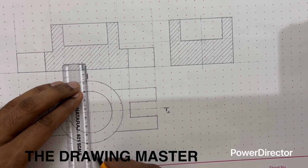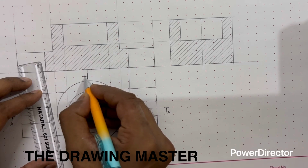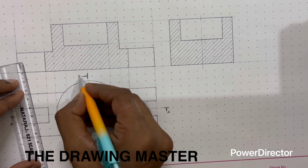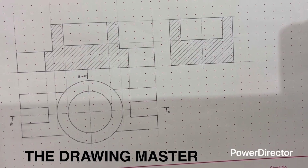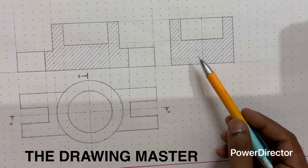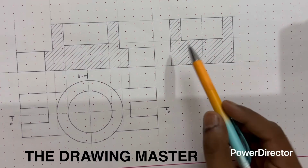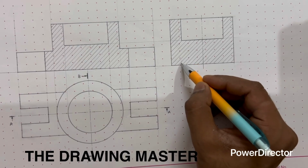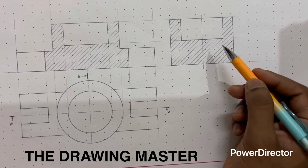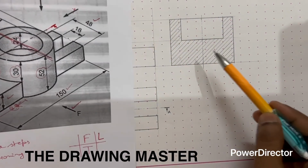This cutting plane line is very important. This is the direction of view and this is the name of the cutting plane, B. So this is the full sectional front view, top view and full sectional side view of the object. And there is one more thing, there is no need to draw the hidden lines here because we are talking about this particular section. Some of you will think we have to draw the hidden lines here, but there is no need to draw the hidden line because we are talking about the particular section of the object. Section is to say this section. So this line will be hidden, so there is no need to draw this.